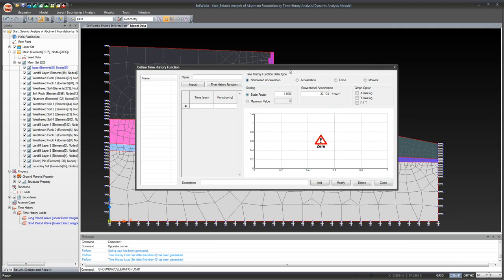As I said previously, you can get your time history graphs from a database, from some public source, and typically they come in a spreadsheet format. So you'll have your graph, but then you'll also have your spreadsheet, X versus Y, and you can import it directly from an Excel spreadsheet using this option here. This allows you to go through your computer and select the Excel spreadsheet you want, or you can even just go to your Excel spreadsheet and copy and paste it directly into here. So Control C, and then Control V in here, and then everything should line up accordingly.